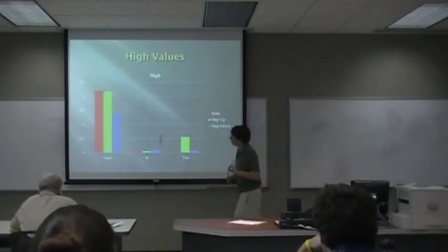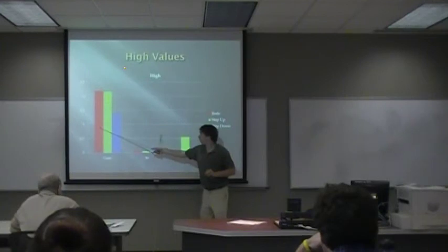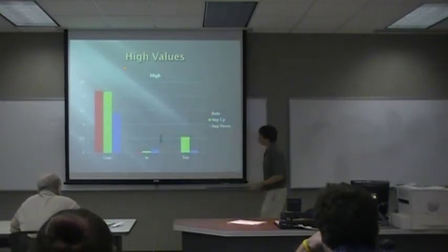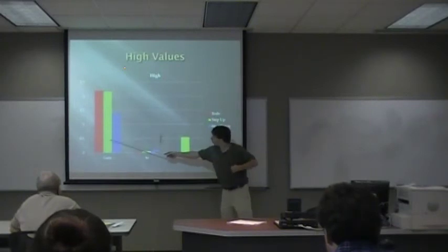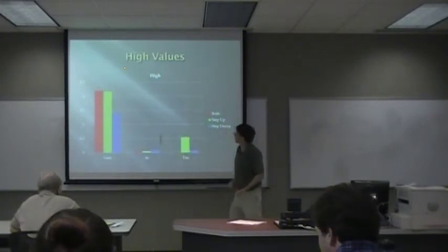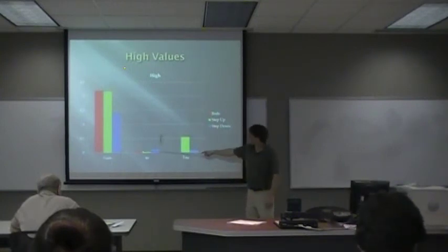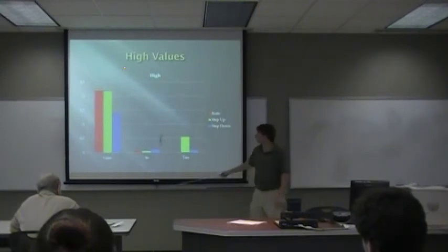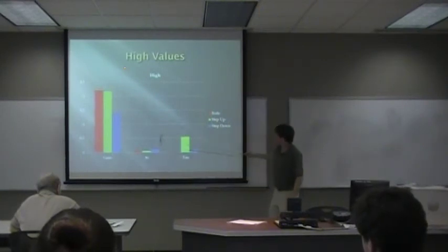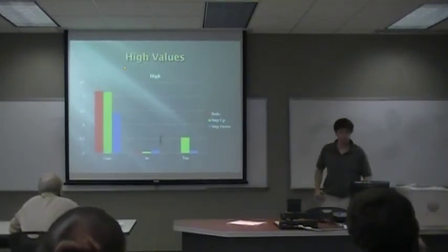And for the higher values, the Bode diagram right here gave more in line with the step up on this one. Step down is a little bit lower. The dead time was pretty consistent, but the time constant was much higher for the step up.